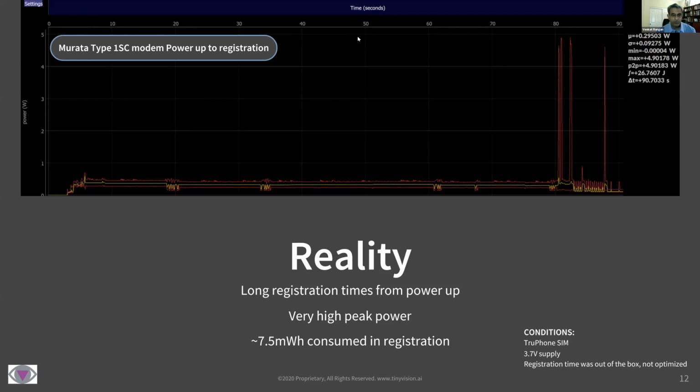So 4G, while its deployment is very easy, you don't have to worry about what the customer's network is, you do need to think about power very carefully. And this can also drive the need for an aggregation node, which is powered. And everybody talks to it through a much lower power protocol, say BLE.